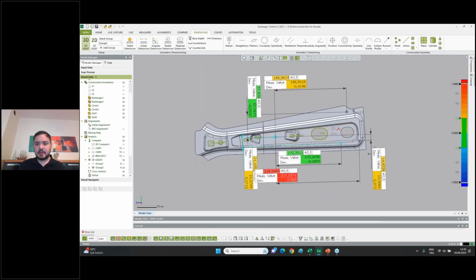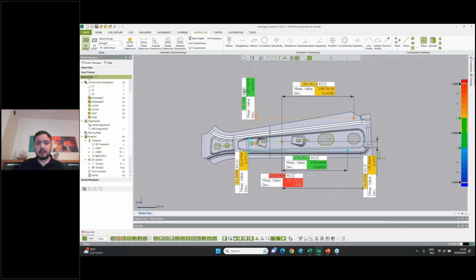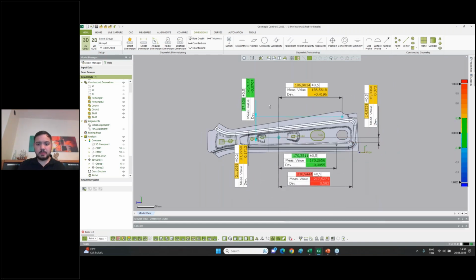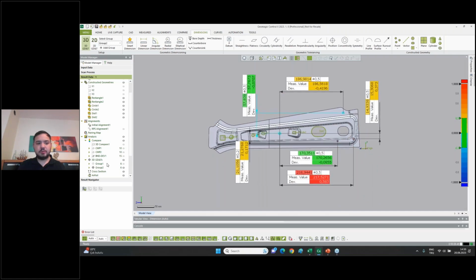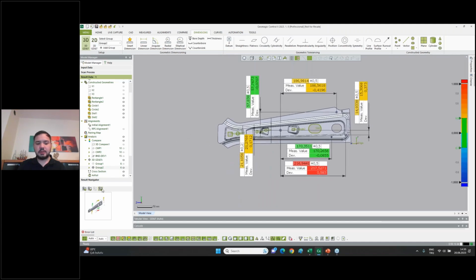I just inspected all the linear dimensions of the part. And as you can see, according to the nominal value, it just gets the tolerance from the ISO standards. So forward, the last thing we need to do is, as always, click group 2 and with the third camera, take the picture for the report.